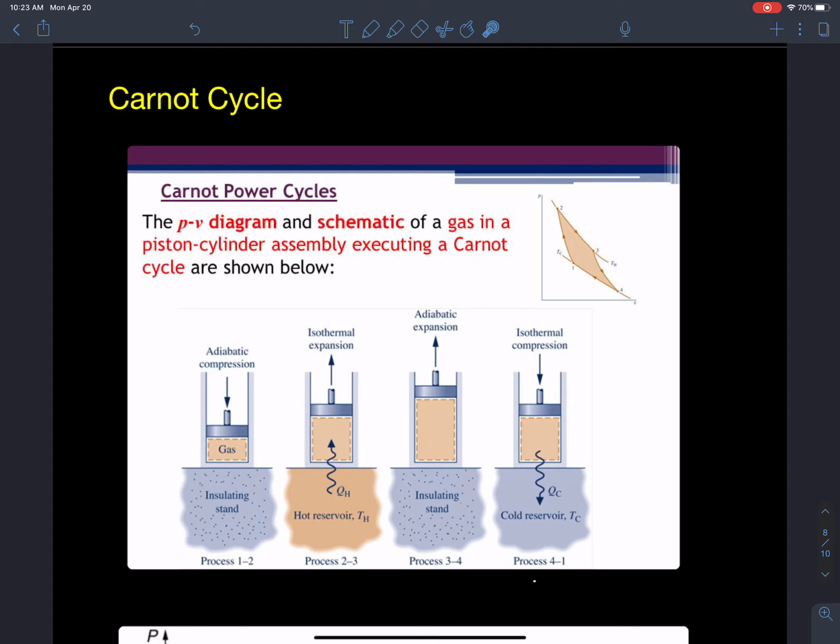And then the other thing that we'd be using is the fact that this piston is going to have some inertia when it's moving, okay? With that inertia, I can cause adiabatic expansion and adiabatic compression processes, okay? So I can be changing the internal energy without funneling heat in and out of the system. That would maximize these jumps over here to try to maximize the area. You notice it's not a straight up and down, it's a curvy up and down. We try to maximize the area under that diamond shape if we can, okay?